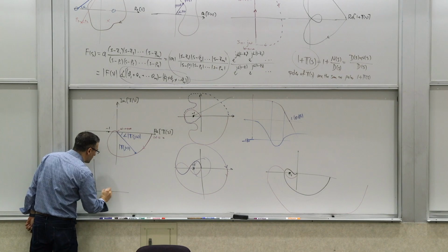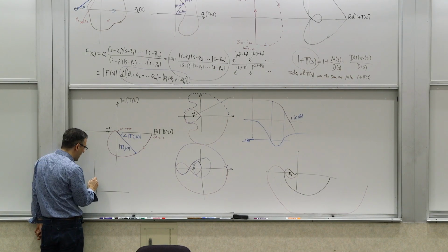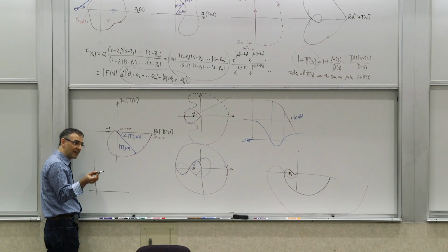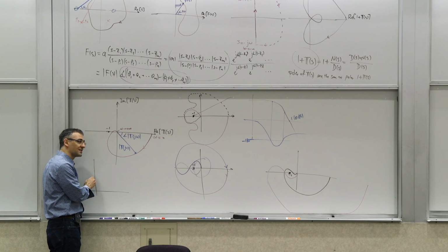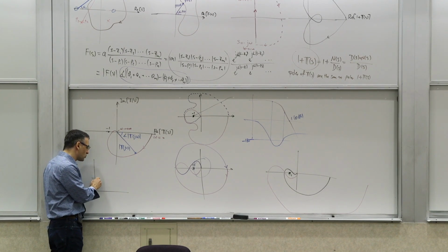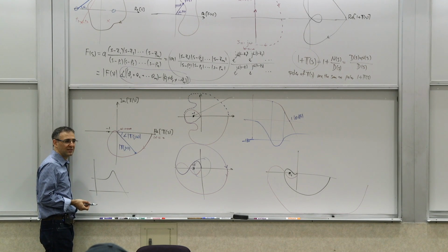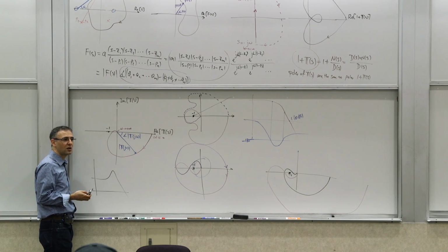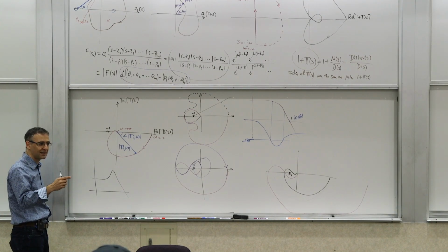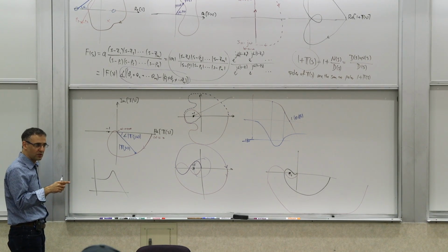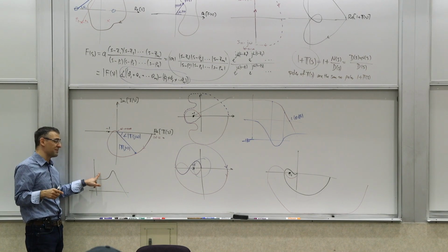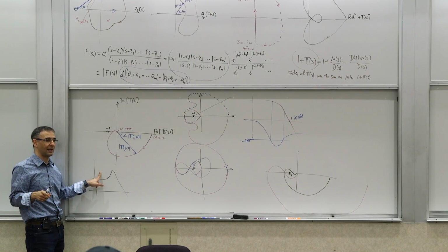But if you look at the Bode plot of the closed loop, right? We saw in that example that we did last time that even when it was unstable, the Bode plot of the closed loop didn't look horrible. It looked like something like that. And the system was entirely unstable because you're talking about two different quantities. And we'll talk about this next in more detail. But it can be actually misleading if you just look at that.